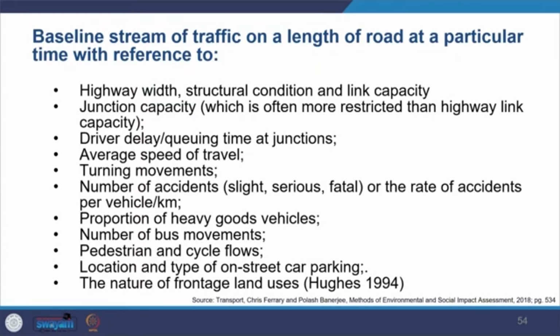It's also required that you describe the baseline of the traffic on the entire stretch which you're working out. And you need to look at all these details: highway width and junctions, the delay which will happen, average speed, the turning movements, number of accidents, proportions of heavy goods vehicles. So all that has to be given. Plus you need to give the number of bus movements, pedestrian and cycle flow, location and types of on-street car parking, the nature of frontage land uses.